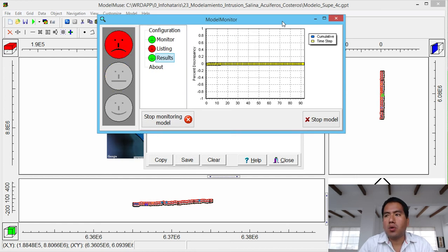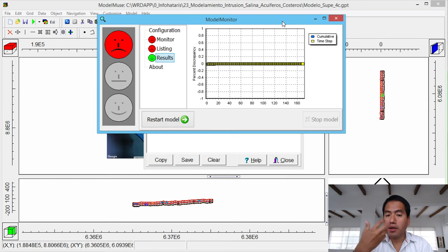However, we have encountered many problems while dealing with this, on numerical instabilities, on hydrological setup, and that's why we don't want you to suffer from the same problems as I did. So we have given this groundwater model that works, so you can learn a lot from what you can get from the model, and then you can deal with the numerical instabilities. Okay, so there are some time steps where you have not reached the closure criteria, but if you can see that the percent of discrepancy is really low,